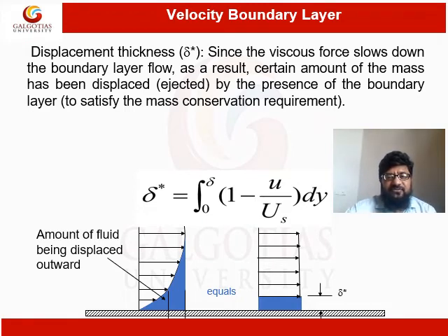Based on this concept, we can derive the displacement thickness as given by this formula, that is the integration inside the boundary layer of 1 minus u over Us dy, where u is the local velocity and Us is the free stream velocity.